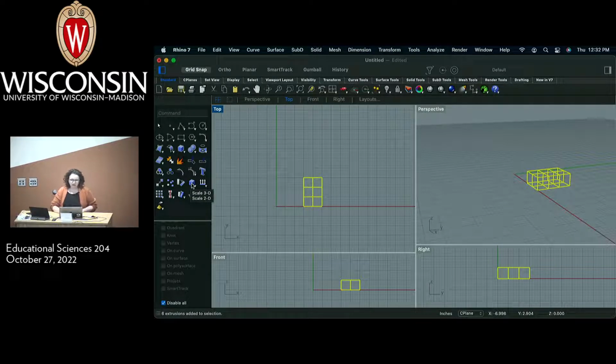And so Rhino, this can be a little bit confusing. Rhino has 3 or 4 different scale functions. So there's 2D, there's 3D, there's 1D, and then there's non-uniform. Pretty much, you're using scale 3D. If you have something in 3D and you want to make it bigger, you use scale 3D. If there are other considerations, like this happens to me all the time when I take photographs of myself.